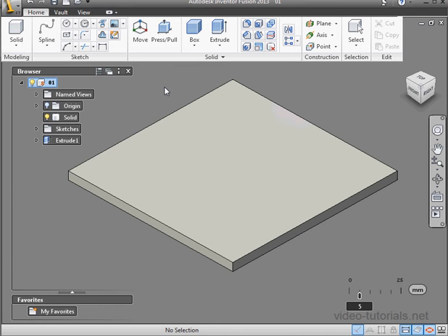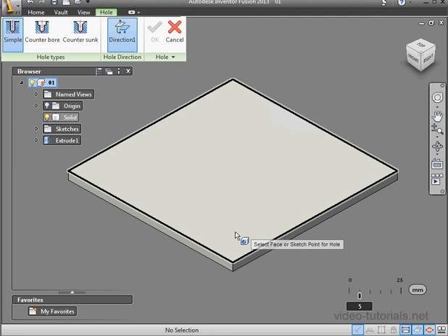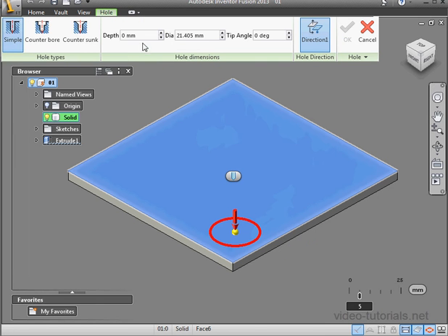In this tutorial, I'm going to show you how to use the Rectangular Pattern tool in Inventor Fusion. Before we begin, let's create a feature that will pattern a hole. The depth will be 5 millimeters, and the diameter of my hole is going to be 5 millimeters also.